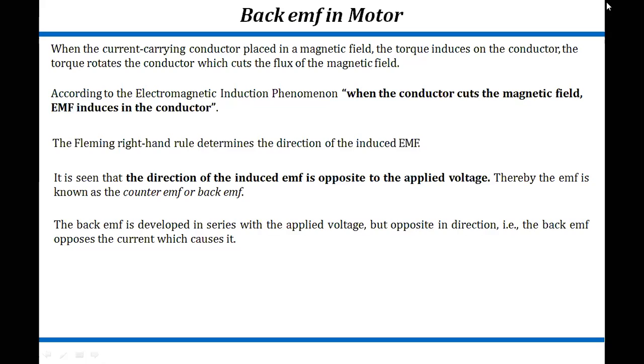When we study the back EMF, when a conductor cuts the magnetic field, according to electromagnetic induction, or Faraday's law, EMF gets induced. So here EMF is generated, but that EMF works in the opposite direction with respect to the supply voltage. And we determine the direction of the back EMF according to Fleming's right hand rule.